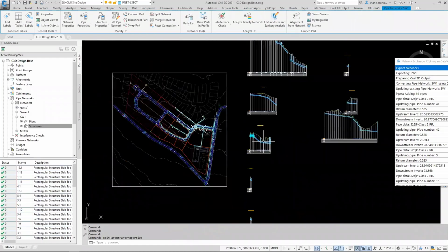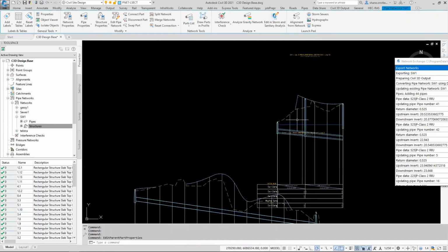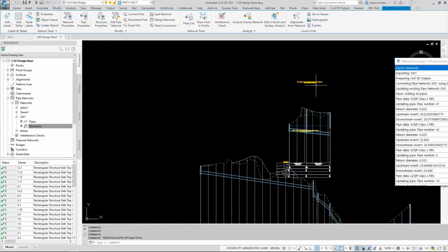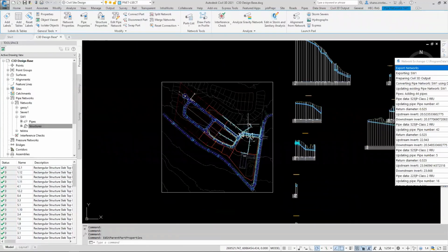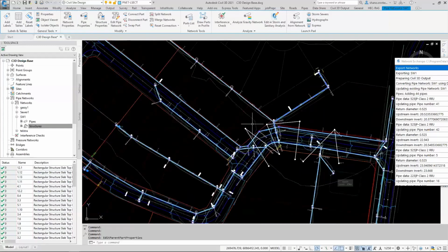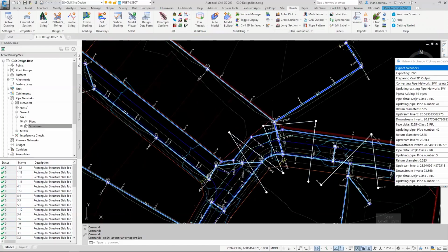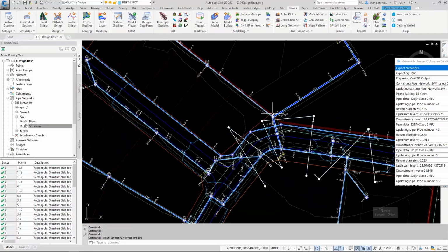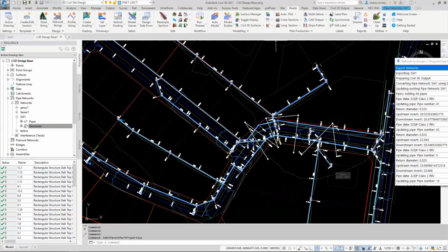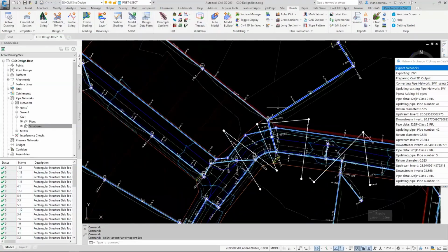There are a few questions about showing the solids in Model Viewer, and Shane showed a method. There are two methods, and the method that Shane showed is great. However, with Civil 3D networks of parts, you can come up with some really quite detailed looking parts for the pits and even different types of pipes rather than just being circular. So what you can do is export the pipe network to solids.